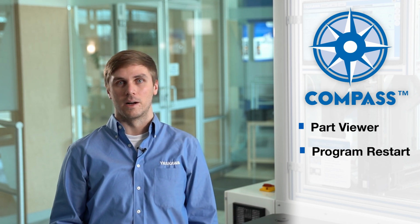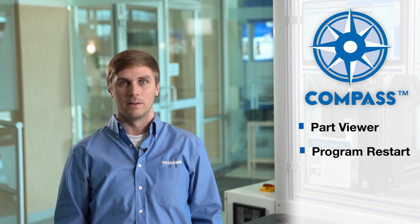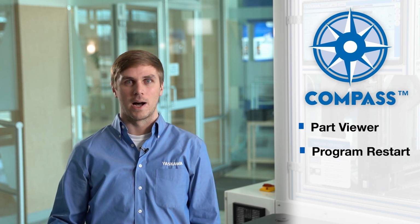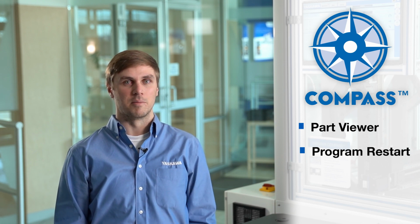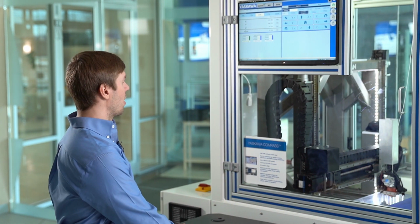The part restart allows us to actually run a G-code file, exit it completely, go do motions such as jogging in manual mode, and then come back to auto mode and restart that same G-code file from where we left off. I'll start with a demonstration on the part viewer.